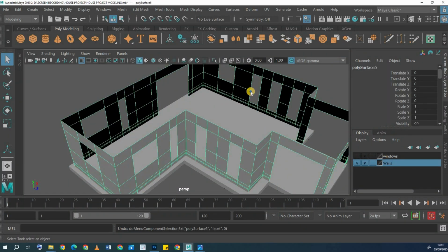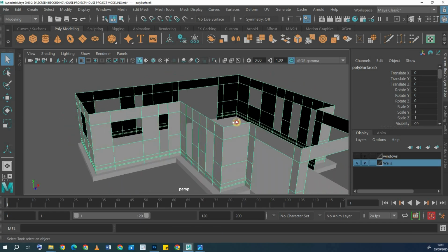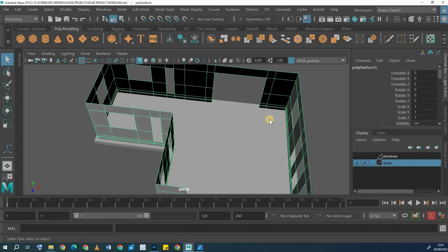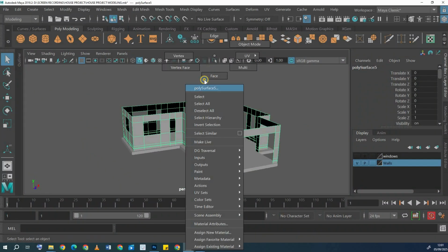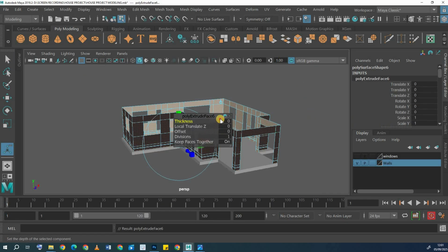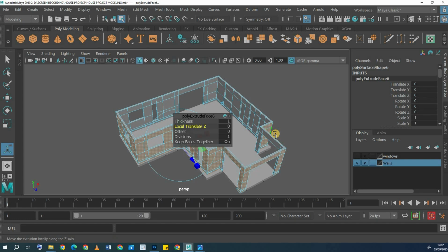So we had this. This is the inside of the mesh. This is the outside of the mesh. That's why Maya gives you black. This one's black, it shows you this is inside and outside. Now, because we're going to make it 3D, if you extrude and put 1, you extrude outwards, so the black goes inside.